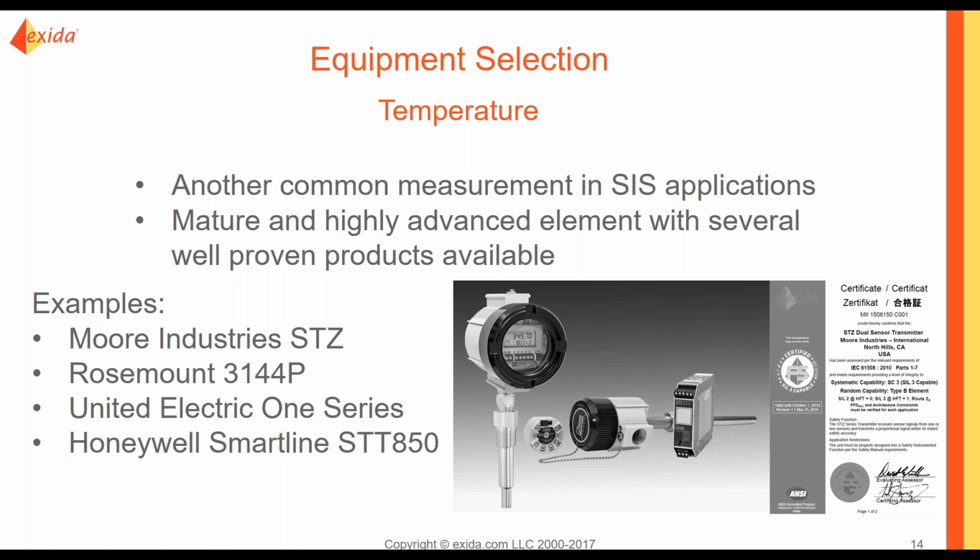This example, this STZ, is rated for SIL 2 in a single application, or hardware fault tolerance of 0, so no redundancy, a 1 out of 1 configuration, and SIL 3 with a hardware fault tolerance of greater than 0 architecture.